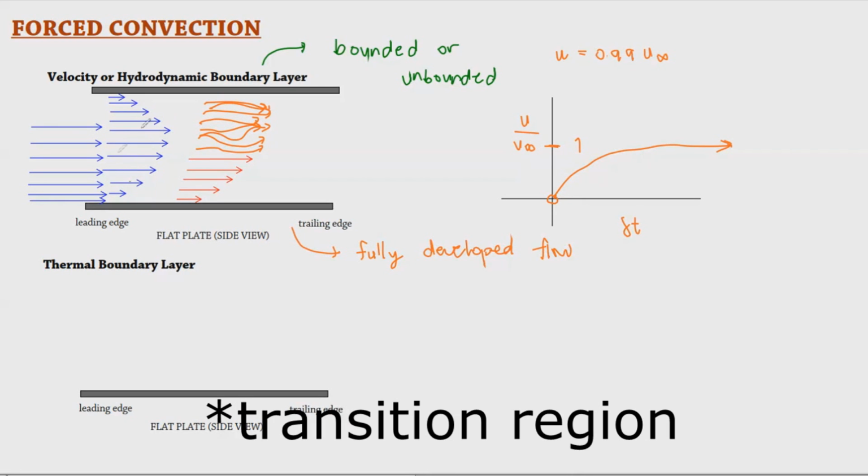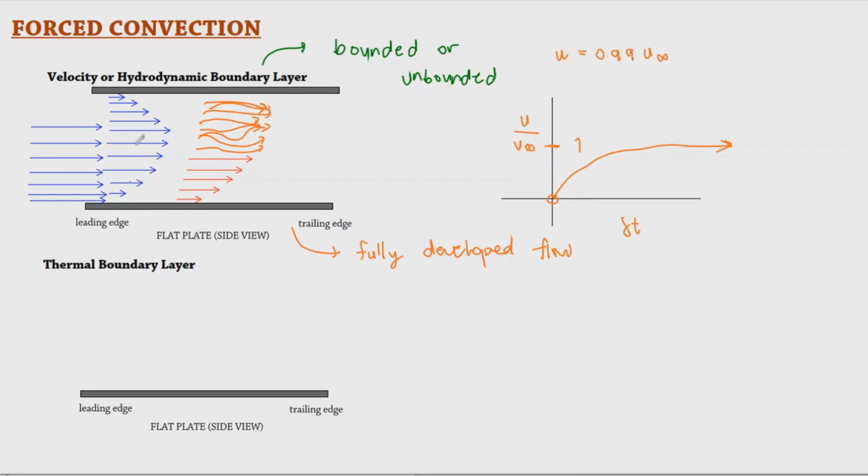And when we have a free stream here wherein the layers are not mixing, I want you to think that these layers are the same fluid, but dissected into infinitely many layers. If these layers are not mixing, we call this the laminar flow, and the Reynolds number for that is 2100 or less. Now if we have some kind of transition region, the fluid layers start to mix up.